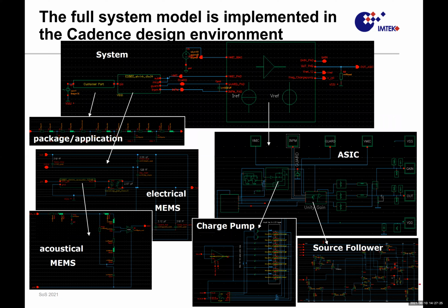Just I give you an insight how those systems are modeled in a professional way. This is in a Cadence environment. The whole system is described for circuit simulators on the ASIC side. We have here the pressure source from outside. A customer port is there, so this might be your phone lid.